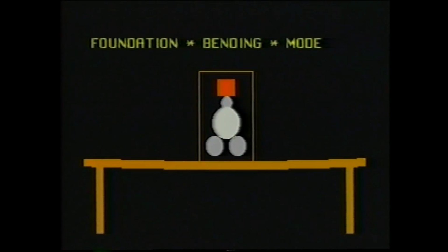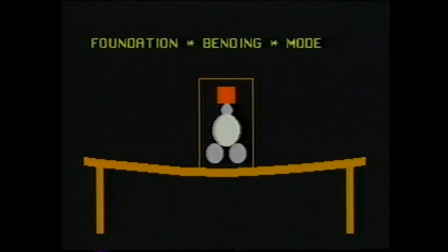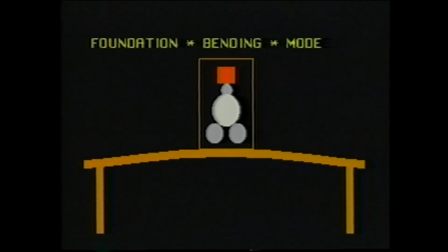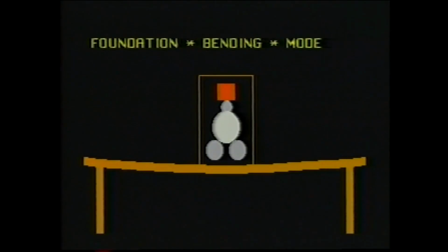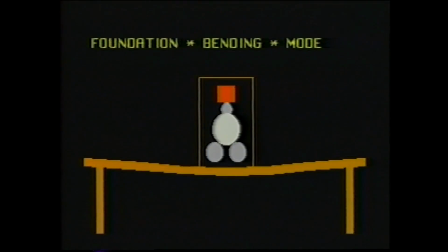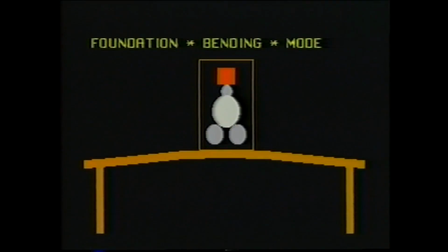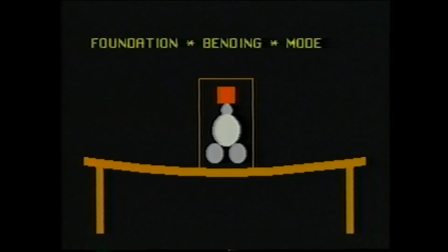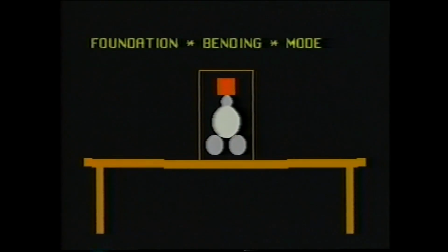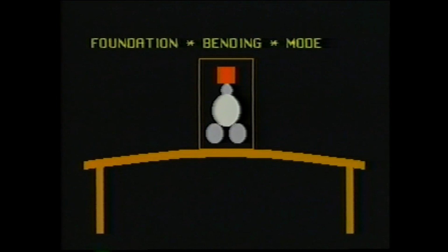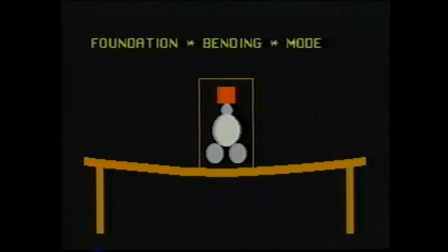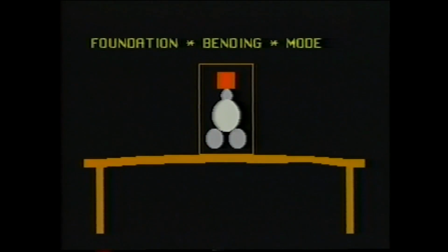Good machine dynamic performance begins with a foundation that is rock solid under all conditions of operation. If foundation vibration can be sensed without instruments, which is about 1/1000th of an inch peak to peak, the foundation is probably inadequate. In the foundation bending mode shown, we can see how the foundation bounces vertically in response to vertical excitation from the paper rolls if the winder is positioned over an unsupported section of flooring.